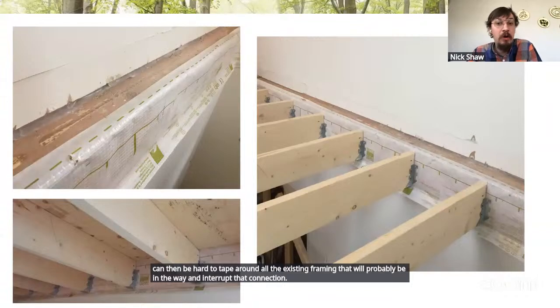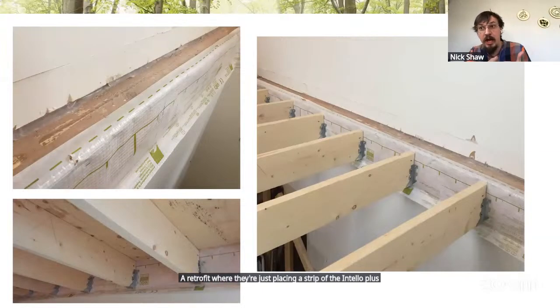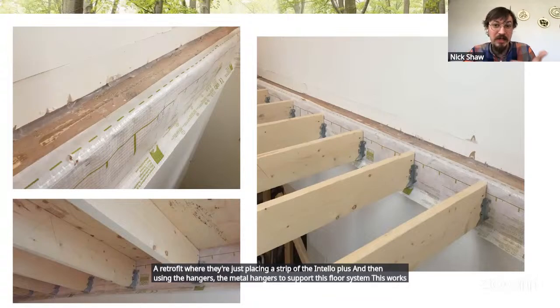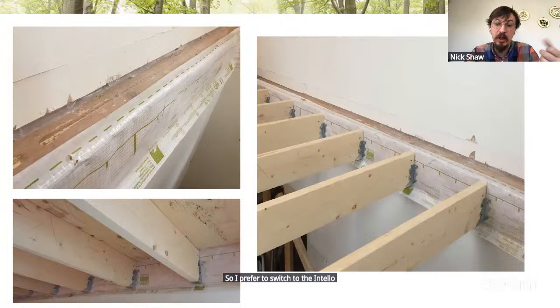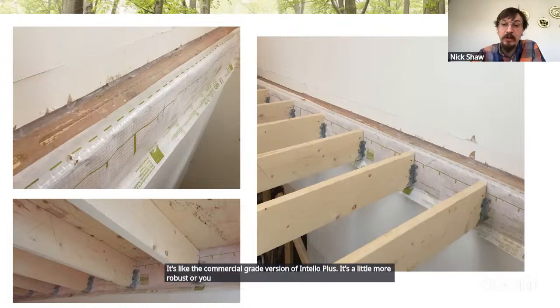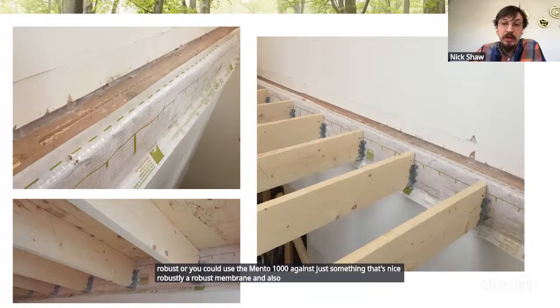A retrofit where they're just placing a strip of the Intello Plus and then using the metal hangers to support this floor system. This works really well, but I am worried about the Intello Plus getting damaged during construction. So I prefer to switch to the Intello X membrane for this transition. It's like the commercial grade version of Intello Plus. It's a little more robust, or you could use the Mento 1000. Again, it's just something that's nice, a robust membrane and also airtight. But this approach does work well.